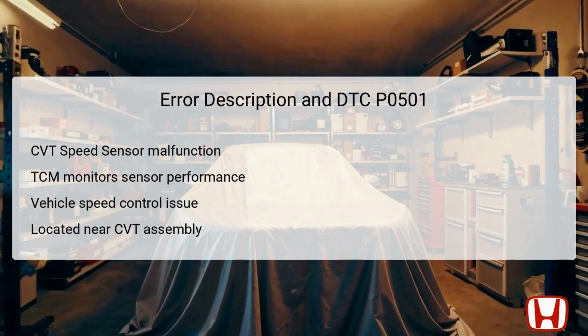The DTC P0501 points to a malfunction in the CVT speed sensor, which plays a vital role in the vehicle's transmission operation. Its main function is to provide real-time measurements of the vehicle's speed to the TCM for optimal performance adjustments. This sensor is mounted near the CVT assembly, traditionally located where it can accurately gauge the drive pulley speed.